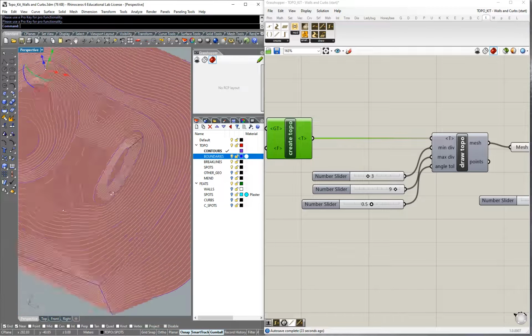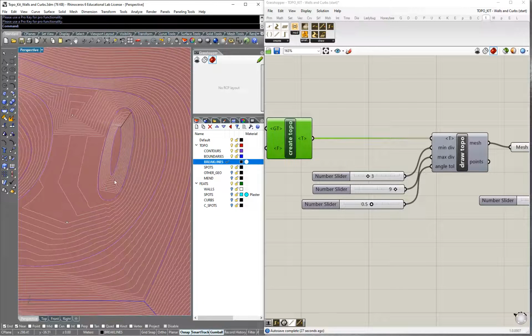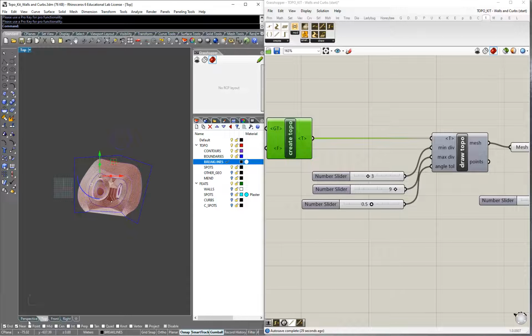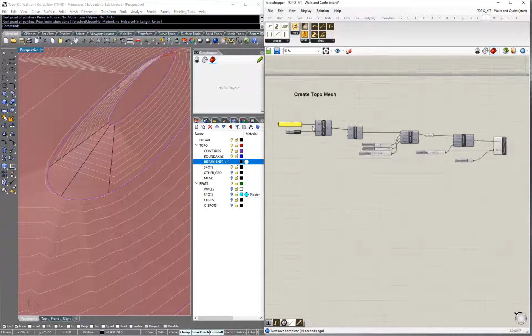So you can add this sort of break lines if you go to this layer and go to the top view or go to the perspective, and then you can add with a simple polyline of 2 points lines that will help to create a curve or a more curvilinear shape. Okay, and now we put refresh.